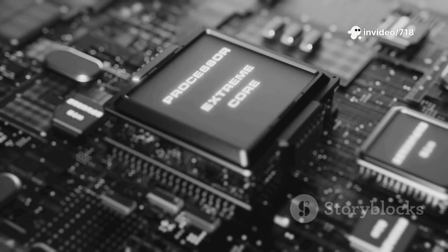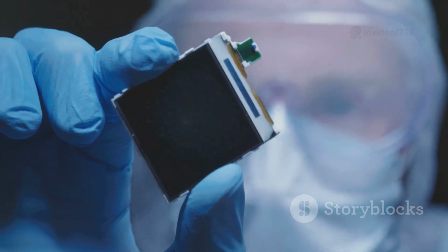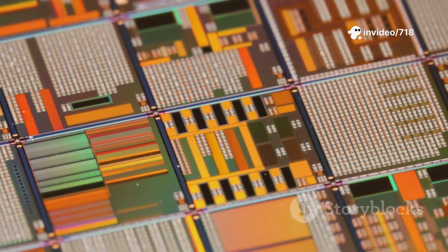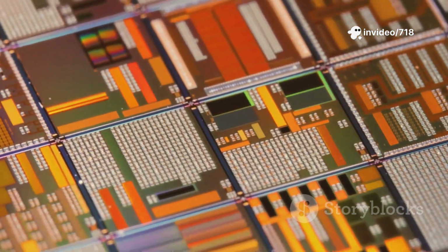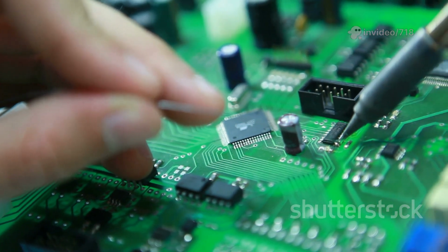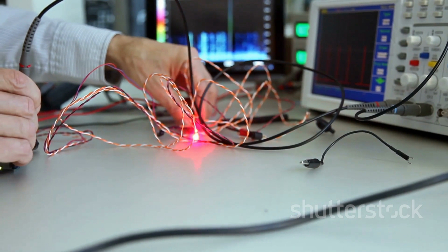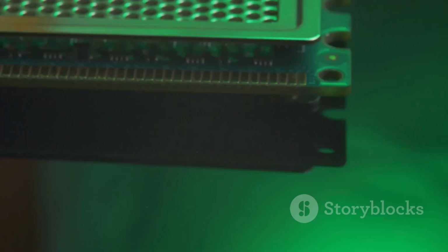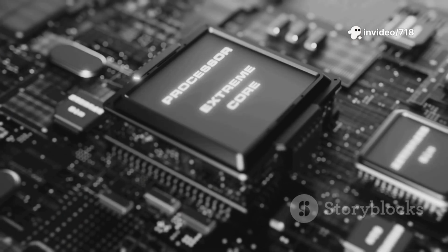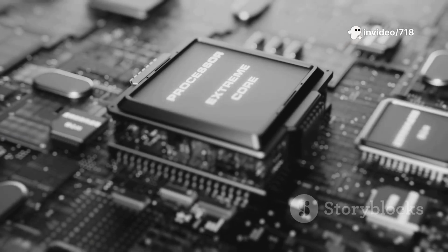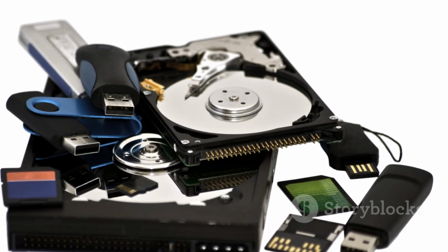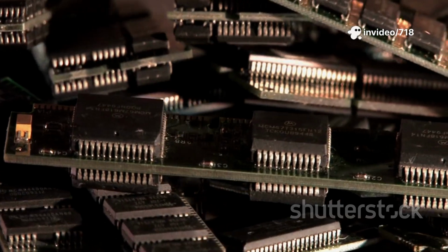How does flash memory achieve this non-volatile magic? It uses a different kind of transistor called a floating gate transistor. This special transistor has an extra insulated layer that can trap electrons and hold them for years without any power. Storing data involves forcing electrons into this floating gate, a process that requires a higher voltage and is known as programming. To erase the data, a strong voltage is applied to pull the electrons out. This is why it's called flash memory, because a whole block of cells can be erased in a single flash operation.